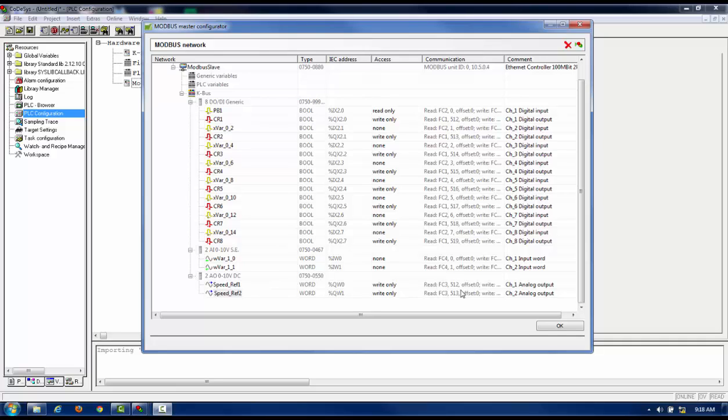So with just using the function blocks by themselves from the library files, we had to define all of this within the function block itself in the declaration editor, using variables and stuff like that as inputs. Here you can see once I've scanned the node, that is clearly defined by the configuration tool, and I no longer have to do that manually, and then we're going to see the function block in just a moment when we utilize it within the actual code.